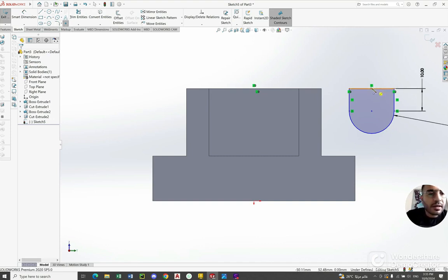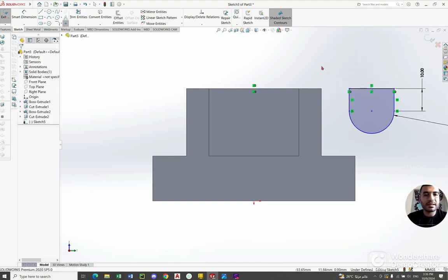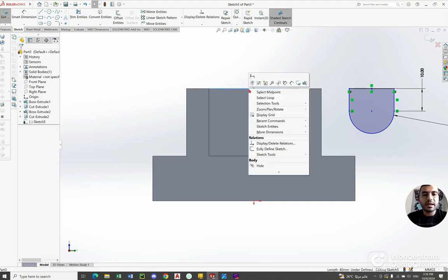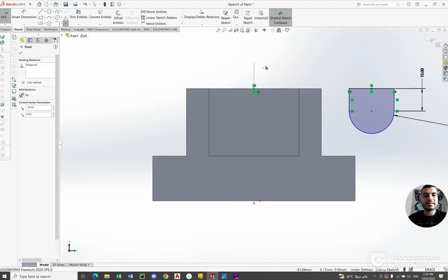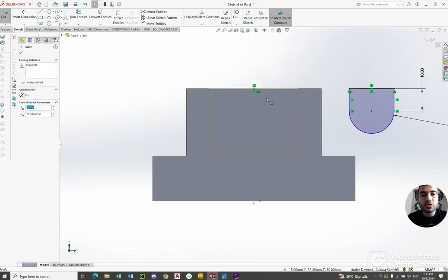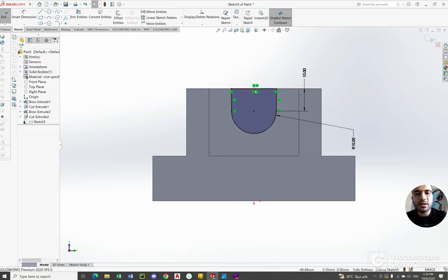We can click here on the line there and insert a point here on the center, like I mentioned, a point in the center there, and in the center right click, select. Then also here right click and select a point in the center, in the midpoint, then Ctrl-click the midpoint line there and click Coincident. Perfect. So now I have obtained the center of this line, and this on the center of this line, the two centers are coincident, so now I obtained this in the center.